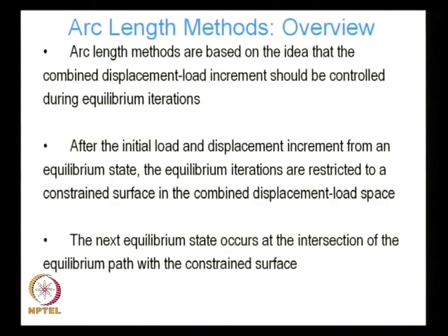Arc length methods are based on the idea that the combined displacement and load increment should be controlled during equilibrium iterations. Not just the load: in a load driven problem we control the load, in a displacement driven problem we control the displacement, but in this case we are controlling both.